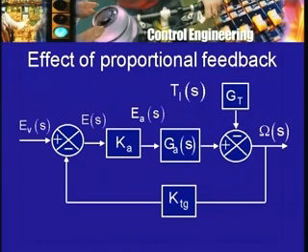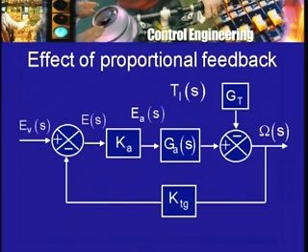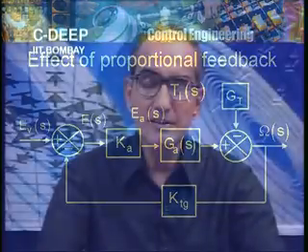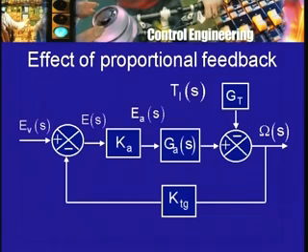It is a prime mover which drives a generator which produces the output Ea, and the field current of the generator is what is driven by this difference between the reference voltage and the tacho generator voltage. So, this is the new block diagram now for the system with feedback. And now we want to find out how it affects the relationship between omega S and TL of S, that is the disturbance. How is the speed affected by the disturbance?